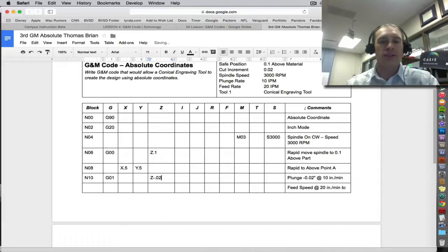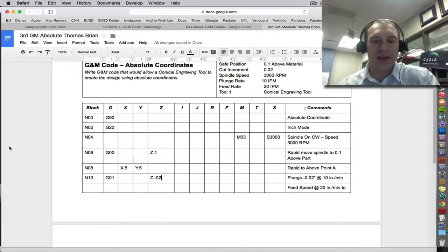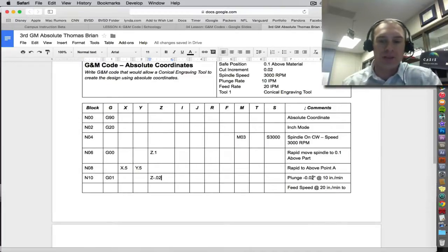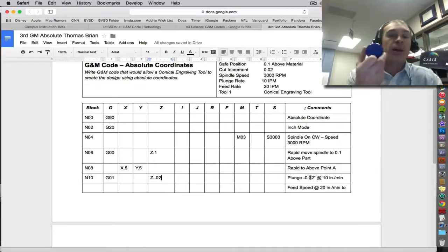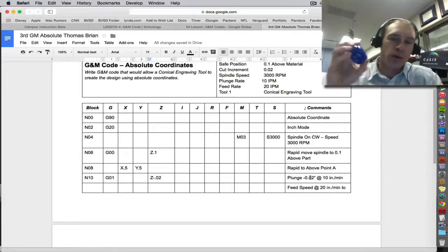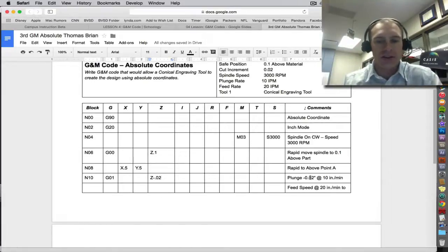We're going 200ths in. When you're engraving, I would actually suggest you go a little bit deeper. So in this sample, we say 0.02. On my milling examples I showed you, this was 0.04. It gives you a deeper line. It's more defined. It's kind of a nicer look. So I'm actually going to do that. I'm going to go 0.04 instead.